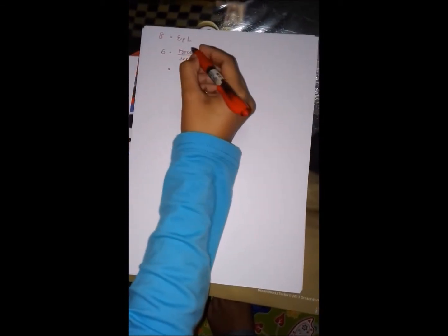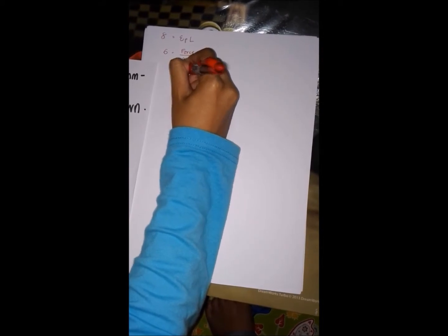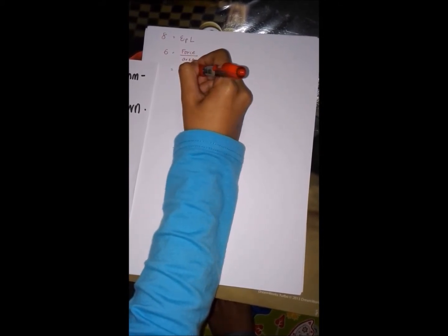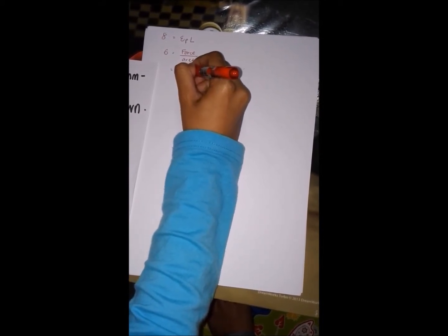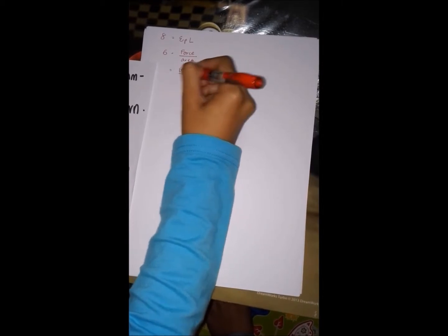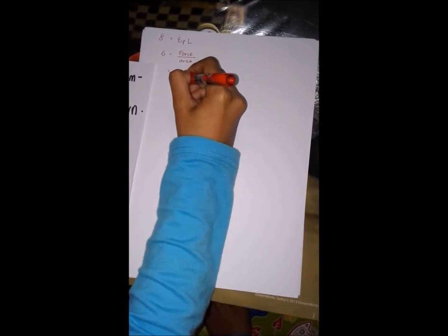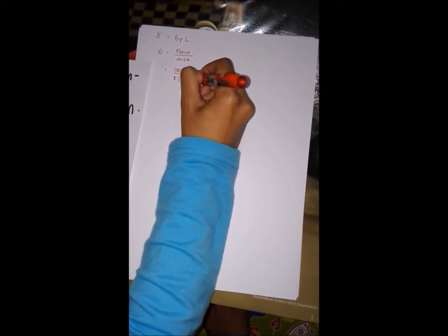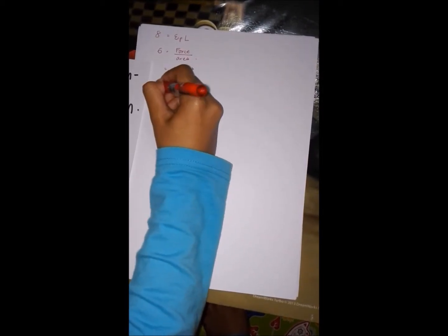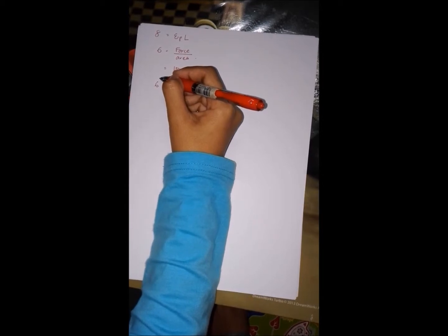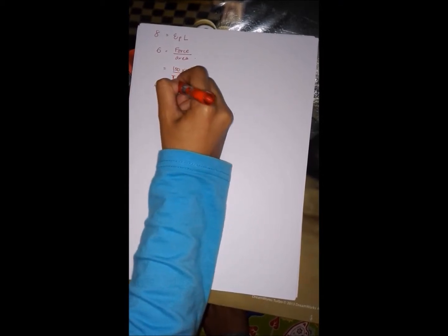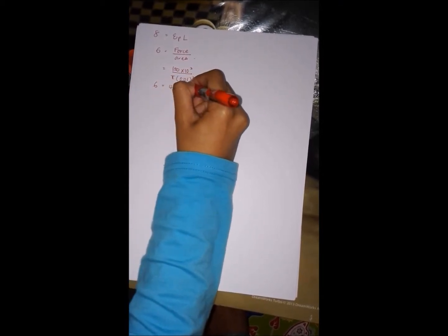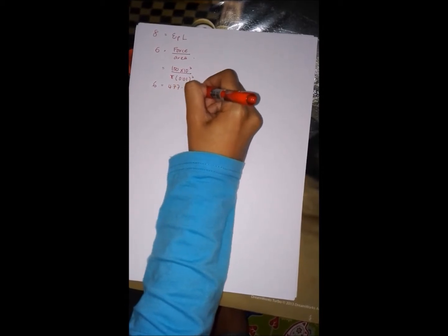The force given is 150 kN over the area, pi times 0.01 squared, and we get the stress is 477.46 megapascal.